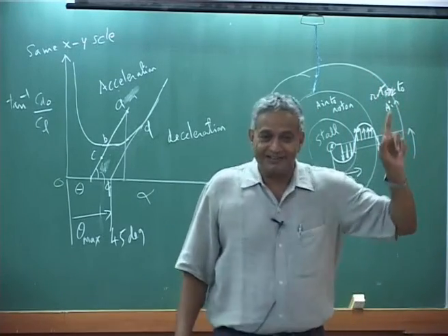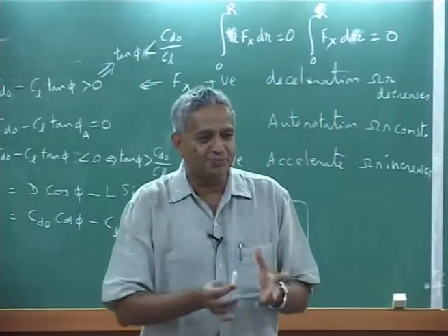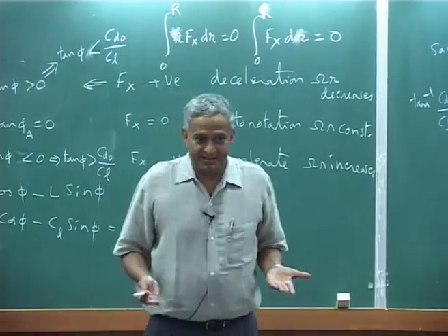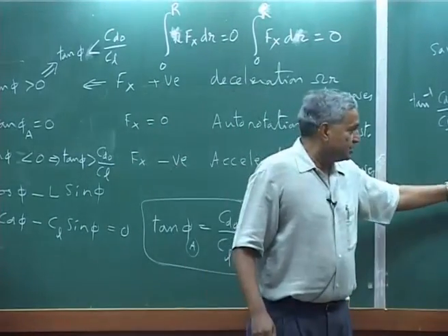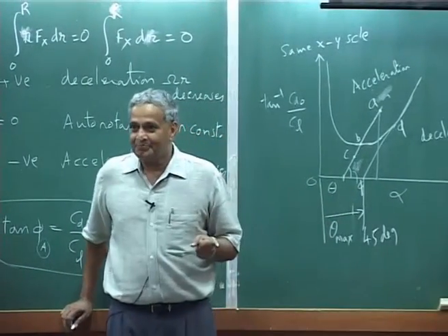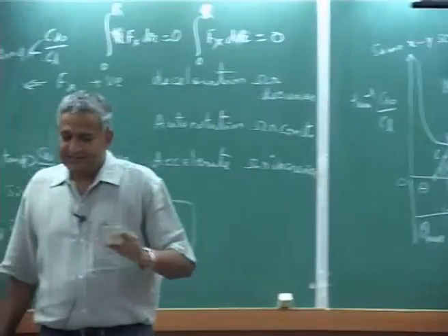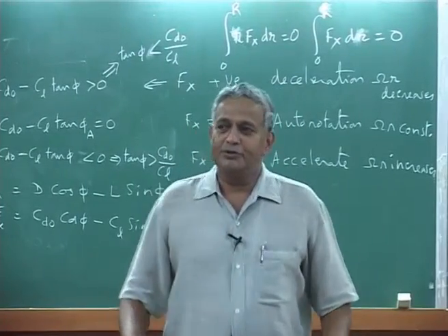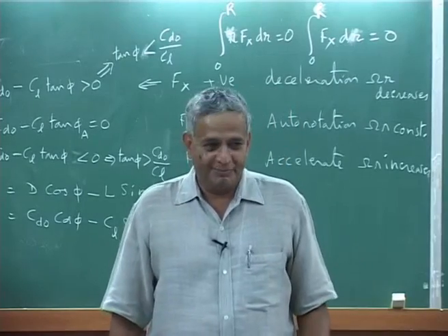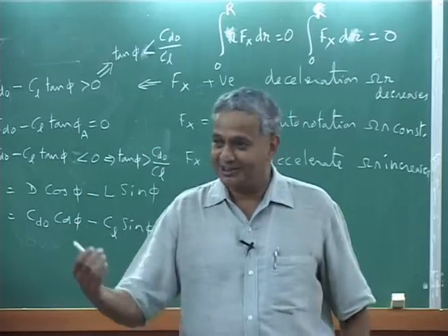They go for power evaluation, not by section, but for explanation from the physics point of view. This is taught because it depends on the aerofoil characteristic, but the pilot is told to reduce. Whenever they say you decrease the collective, the general tendency is, if you want to go up, what do you do? You increase the collective, provided the rotor is in attached flow, lift will go up.